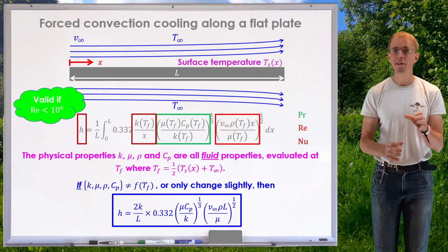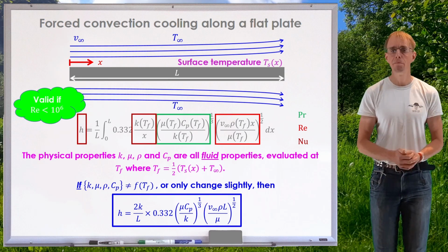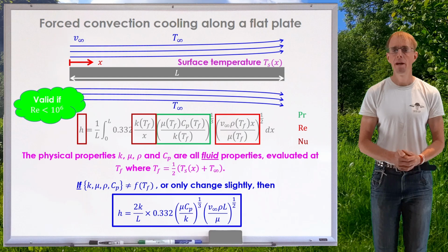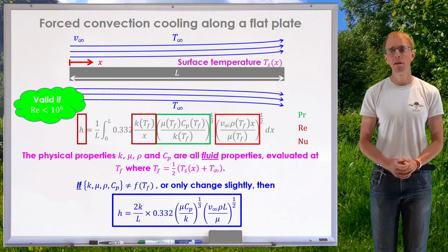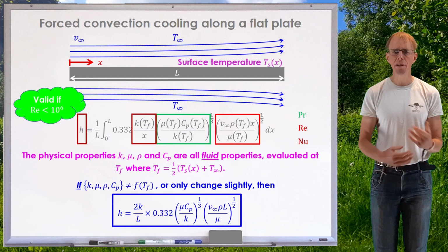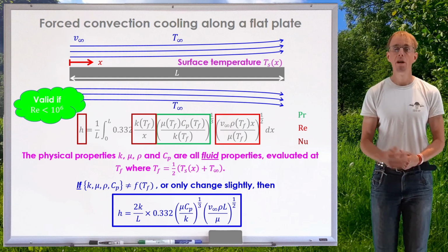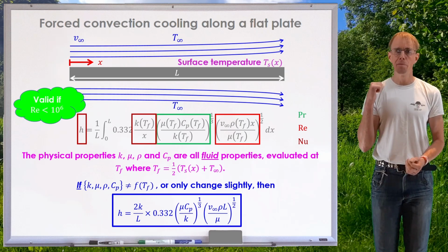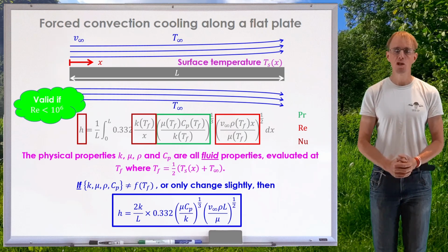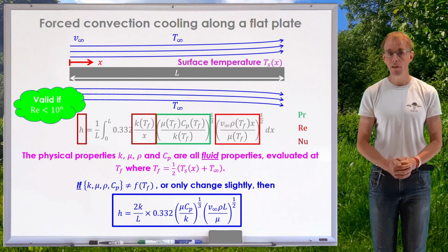And if we look at where that distance x manifests, we have it in the denominator of the Nusselt number, highlighted in brown, and we have x to the half in the numerator of the Reynolds number, highlighted in red. And if we think about that, this effectively becomes an integral of 1 over root x, which gives the result I've shown there on the board. And so we can see now that my heat transfer coefficient, h, is effectively independent of length, x.